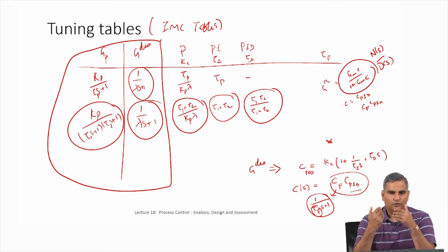And then we also took the same state space equations and multiplied by e to the power minus st and showed you the Laplace transform, and showed you how the differential equation state space models get converted into algebraic equations. And once we have these algebraic equations in the Laplace domain, we showed how the convolution solution in the time domain becomes simply a multiplication solution in the Laplace domain.